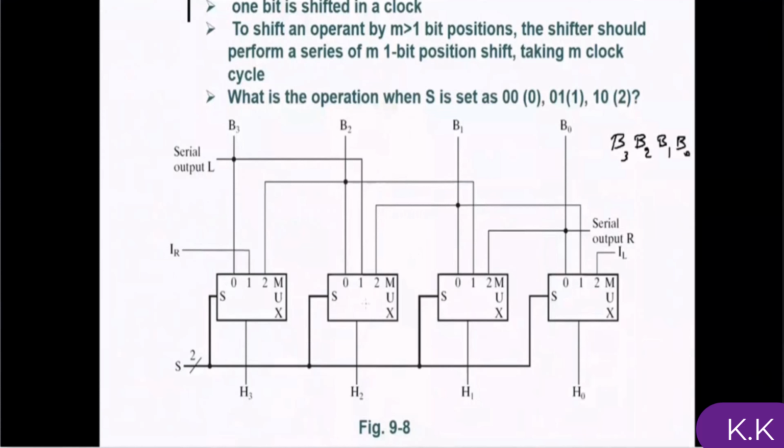What about the shift operation? There are two different ways to design a shifter by using a simple combination of circuits. As you can see, as inputs we have B3, B2, B1 and B0. There are 4 multiplexers. Actually they are 4 by 1, but it doesn't display the next one. So we have 2 bits of value for the selector.